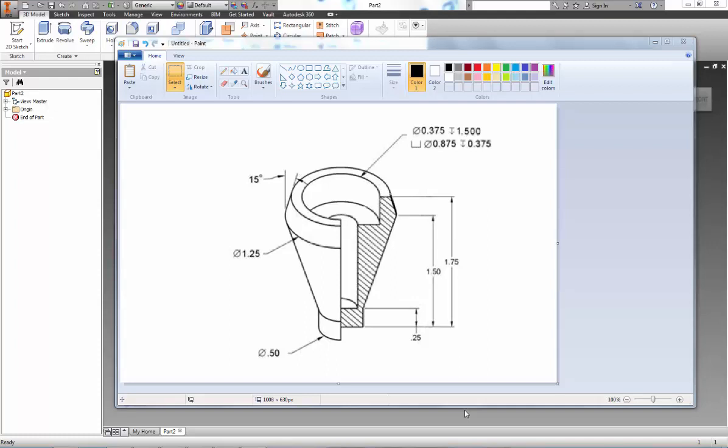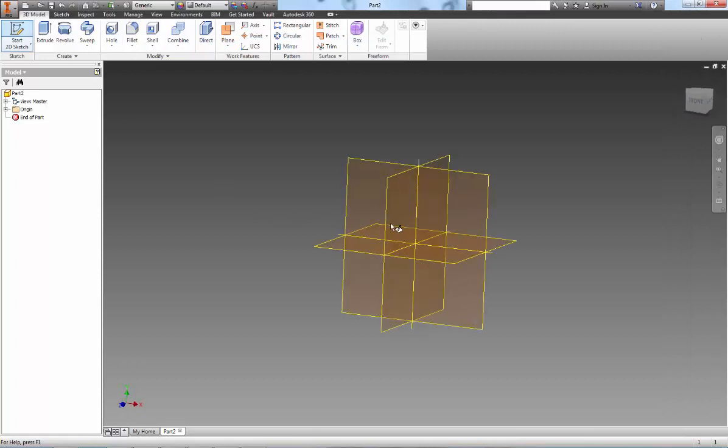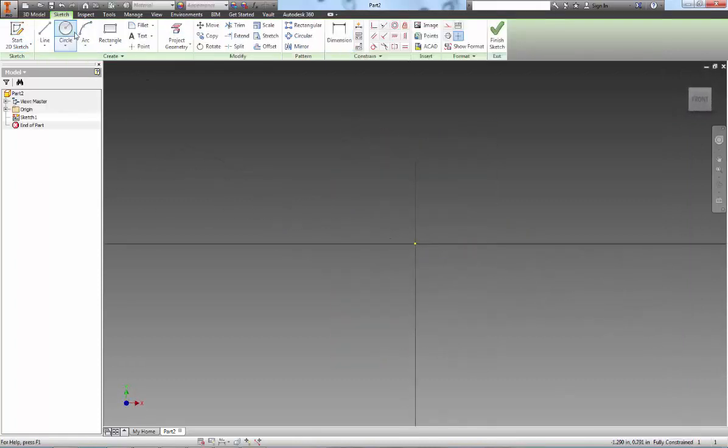Okay, when designing the smokestack, what we're going to want to do is draw out this cross section. A good rule of thumb is whenever given a cross section, you typically want to draw that because that's going to essentially give you the basic shape, and then we can simply revolve that shape to get the entire form. So back in Inventor, I'm going to quickly draw out that relative shape, and it kind of looks something like this.